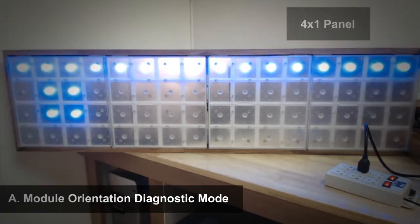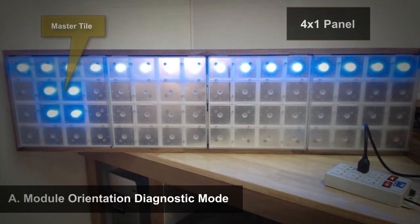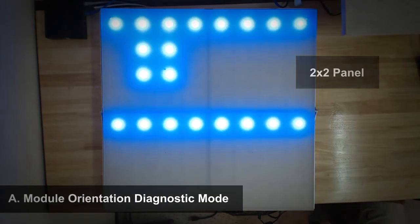The first part of the boot up sequence is the module orientation diagnostic mode. A blue line appears across the top row of all the modules, and the master tile additionally lights up, in the same blue, its middle 4 LEDs. In a correctly configured panel, the blue lines should all be oriented in the same direction, and there should only be one master tile.